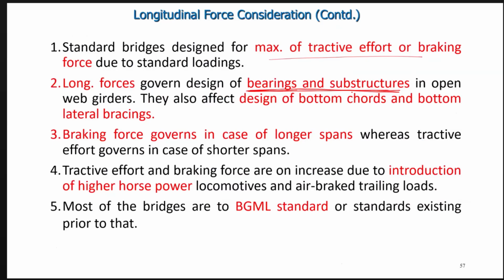In the substructure, the whole substructure has to be checked, and in open web girders, the longitudinal force is important for the design of the bracings and the load transferring system. They also affect the design of the bottom chord and bottom lateral bracings. Correct. Braking force governs in the case of longer spans, whereas tractive force governs in the case of shorter spans.